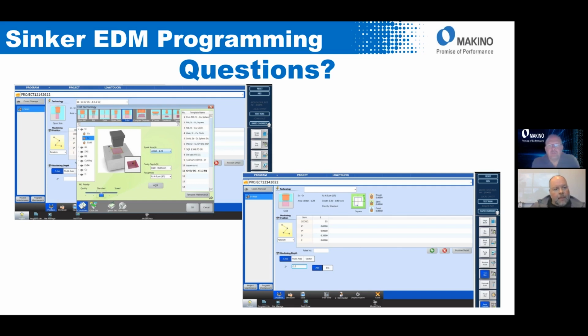All right, very good. And then Cody has a question. Is it possible to burn a helical profile? Yeah, actually, very simple as well. Up in the technology section, edit technology, there is a section for helical, for gear machining. Really, all gear machining is more of the movement of the machine, what we call ZC movement, where we synchronize the Z and the C. We'll have X amount of revolutions in the C to match the Z depth. The jump motion is also that same ZC reverse path.